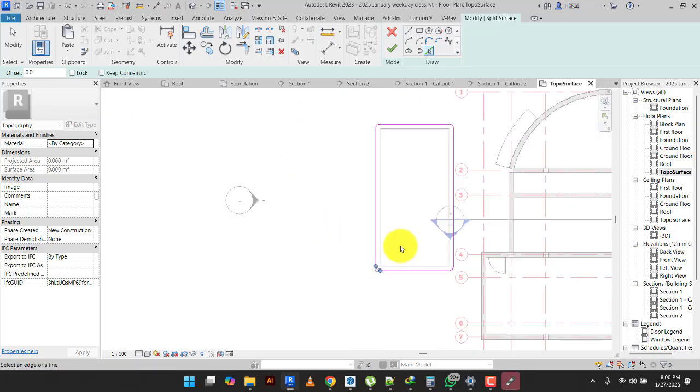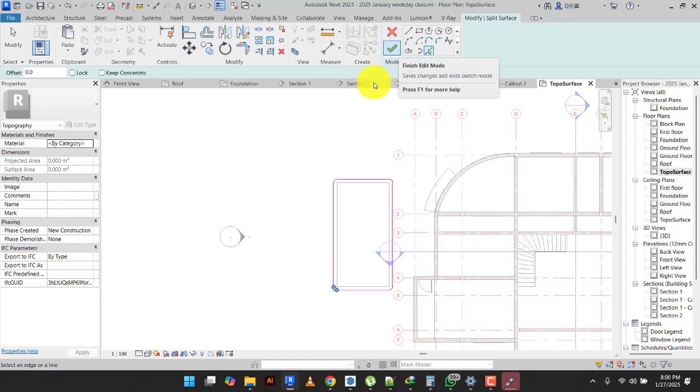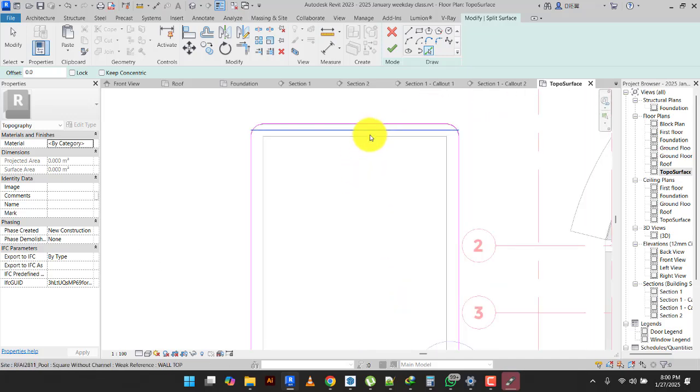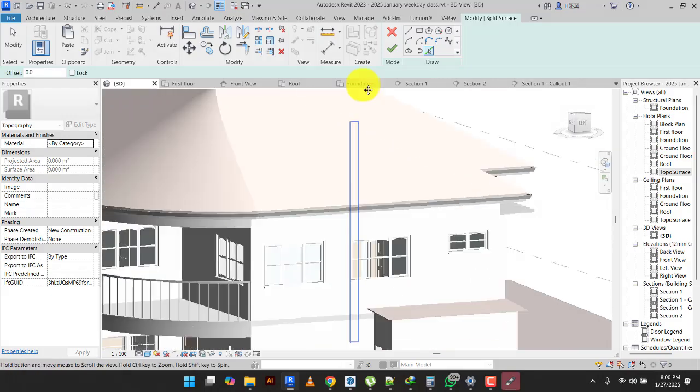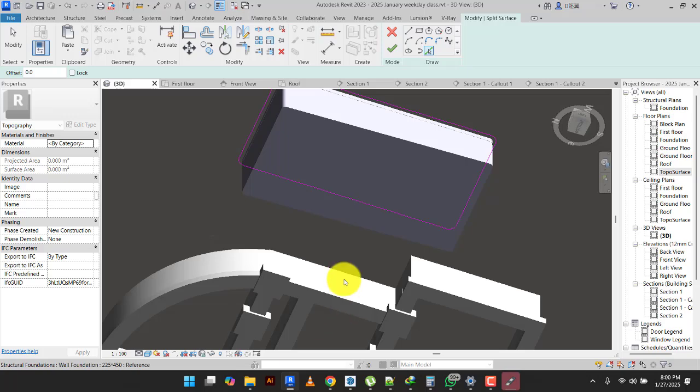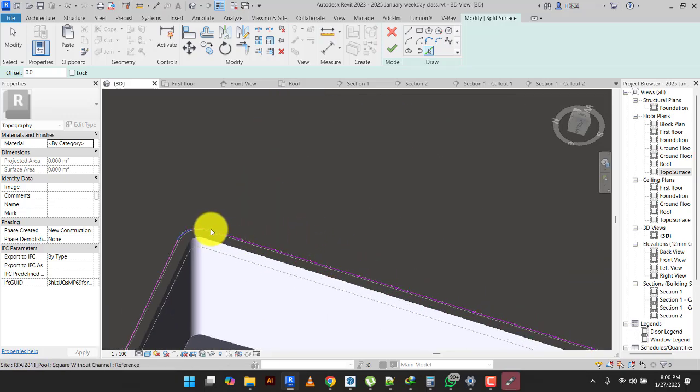After selecting the line, you accept, right? See, I'm picking the outside line. It depends. It could be I'm wrong. I'll be wrong if, you see, sometimes this will be the shoulders. Shoulders fall on it. If this is the shoulders, it means you have to pick the inside. Are you with me? Let me go to 3D and look at this one. It's shoulder, eh? I also think it's shoulder. Let's see. It's shoulder. You can see, this is the body itself. So what we are picking is wrong.